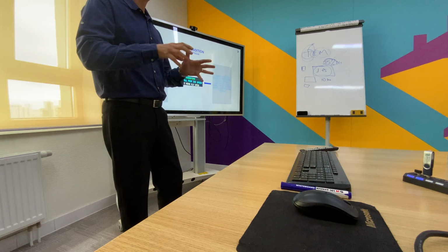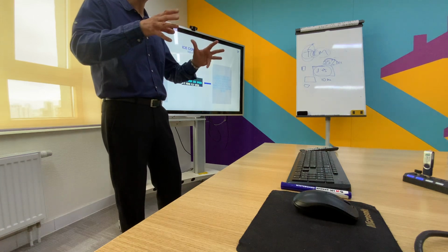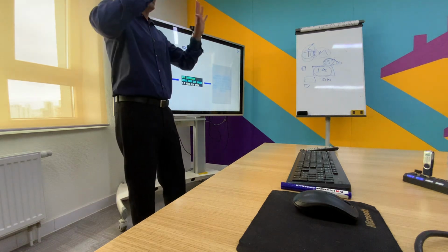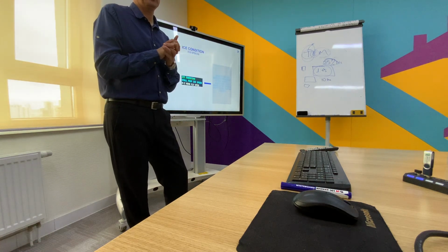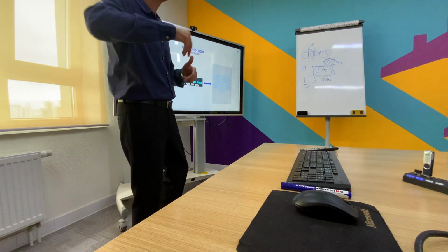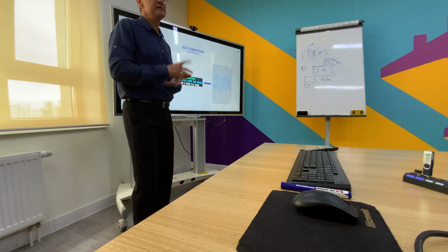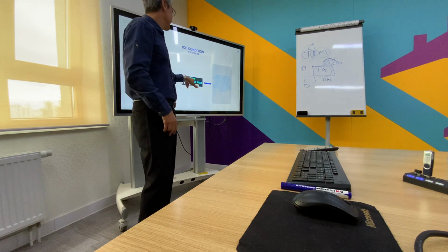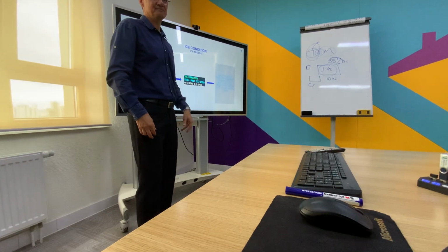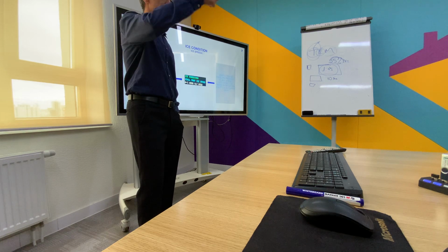So if you face a situation like this, good weather and an ice condition, maybe we are flying in an envelope for ice, for normal ice. Then this will be triggered. That's not a big deal. After you select a normal climb rate and a normal speed, it goes away. Okay? And you have to reset the stall protection ice speed, because it will stay there until you reset it.